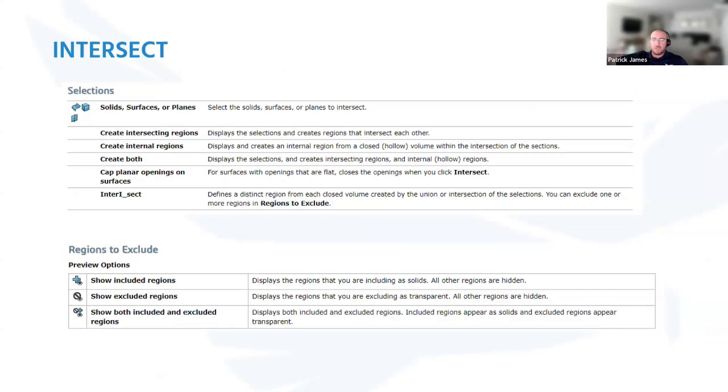With the Intersect tool, we can use solids, surfaces, or planes. So those are all fair play. And you can choose to keep stuff in the tool, or you can keep everything and just choose from the solid bodies folder later. So unless I'm specifically just combining two things, I'll usually gravitate toward the Intersect tool just because it's more capable and I can do cool things like cut with a plane.